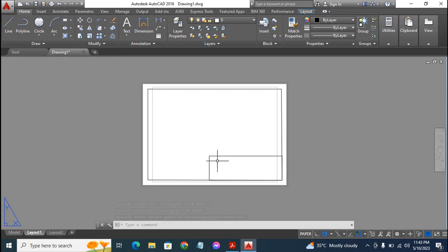Next up, we want to start demarcating this. We are going to be getting horizontal lines at a distance of 10 millimeters. So we are going to be having 5 segments. All right, so let's do that. Go to the draw toolbar, click line. Then I want to draw a horizontal line here so that it will enable me to offset. All right, so lock it to this point of intersection, then press escape to exit. Now I've gotten a horizontal line.